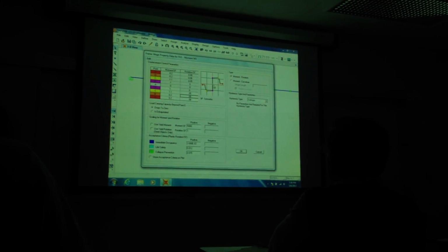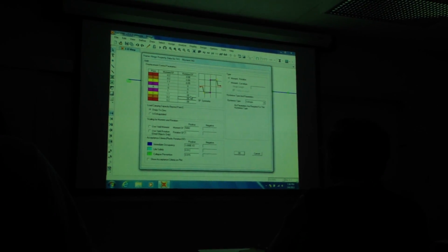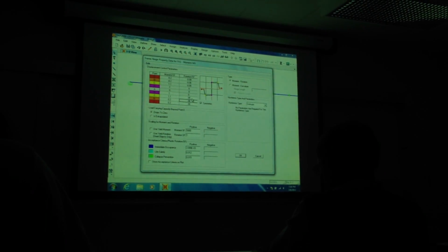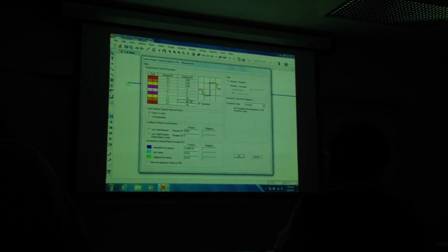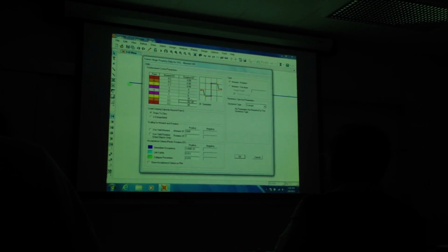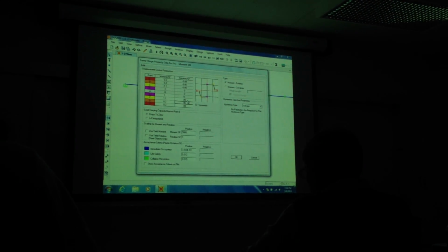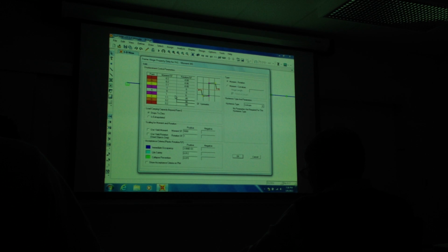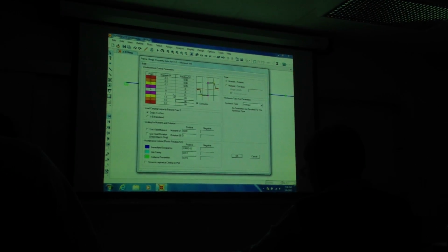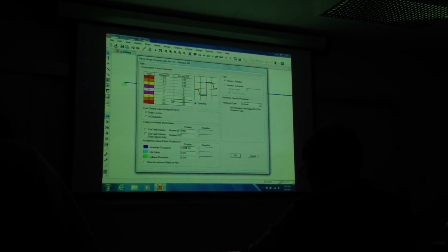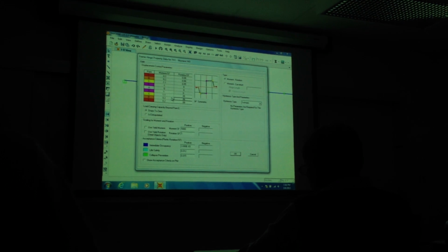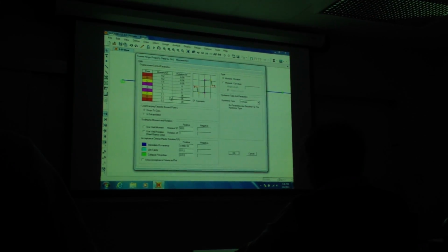But if it exceeds this point or this point, which I gave it, I said, okay, 0.05 radians. And what that is, the ultimate curvature minus the idealized yield curvature of your section, multiplied by a plastic hinge length, like the equivalent plastic hinge. That gives you a plastic rotation. The ultimate curvature is based on the strain capacity of the concrete in compression and the rebar that's inside the concrete, whichever one reaches its capacity first.